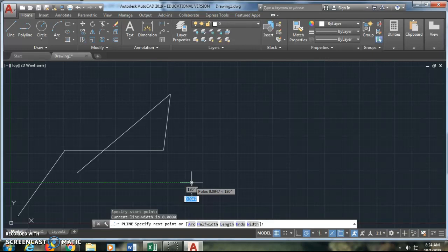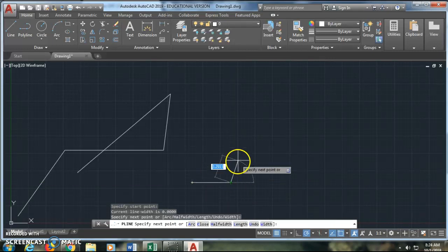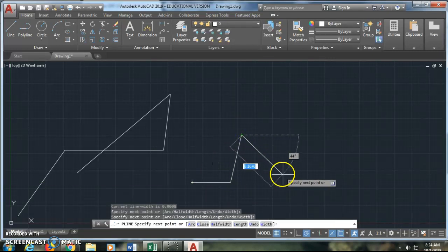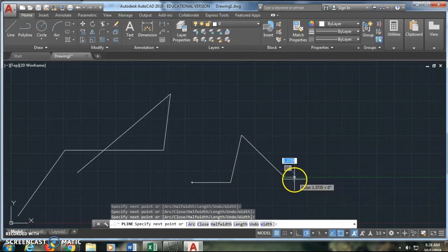What you have to know is that because it is a polyline, if you were to explode it so that you could edit just one part of it, you would then be getting rid of the width factor. Alright, so here's an example of that. You can click on the screen, and however many places you click, you will see. Then I could give it a width at this point by typing W, and I can say I want the starting width to be 1, for example, and I hit enter, and then it's going to ask me what I want the ending width to be.